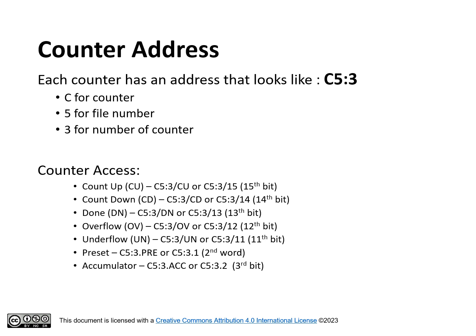Preset, C5:3.PR, or C5:3.1 on the second word. Accumulator, C5:3.ACC, or C5:3.2 on the third word.